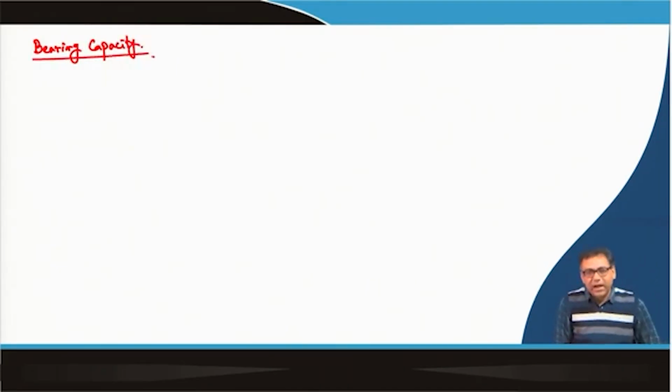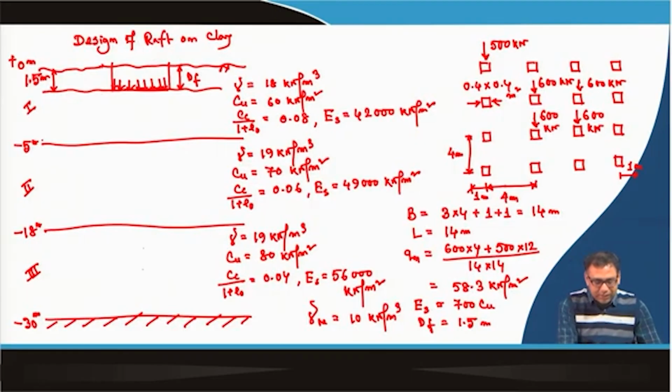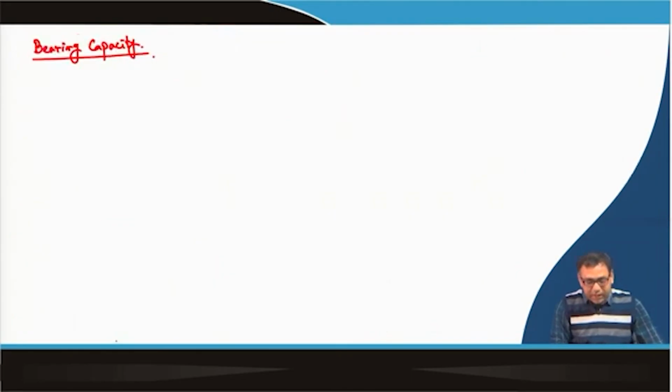Okay. So, as I have mentioned during my bearing capacity discussion for shallow foundation, it is better to use two bearing capacity equations. Here it is only clay, so I have decided I will go for the Skempton bearing capacity equation, which is applicable for only clay, because all the layers are clayey soil. Then I will use the Hansen bearing capacity equation, and then we will decide which value we will use. So, first we will use the Skempton.